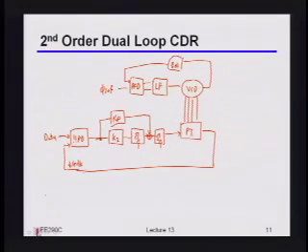So again, just to make sure the intuition is clear, this register here would be the frequency register, and that output over there would be the phase register. The frequency register tells you what the ppm offset is between the two clocks, and the phase is telling you what the instantaneous phase value is that you should be using to control this phase interpolator here. Okay? Does this make sense to people?